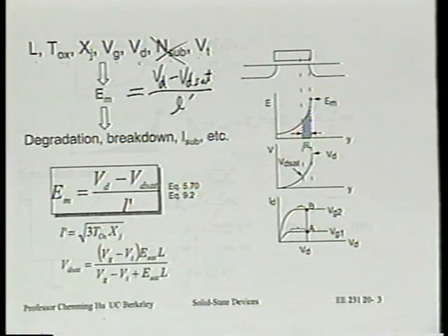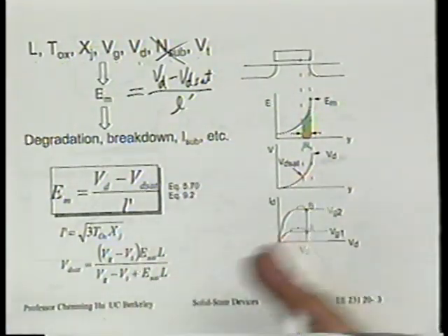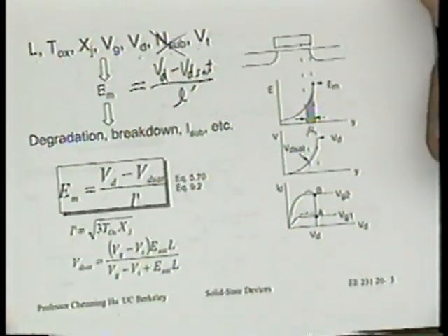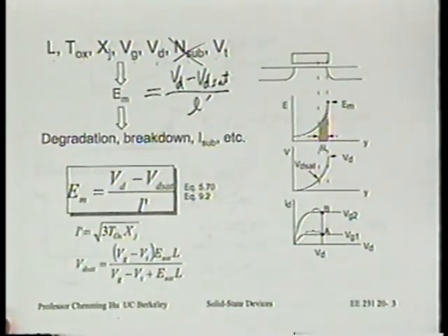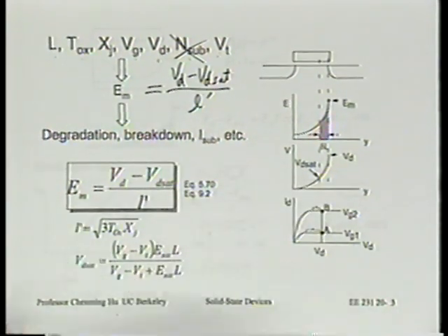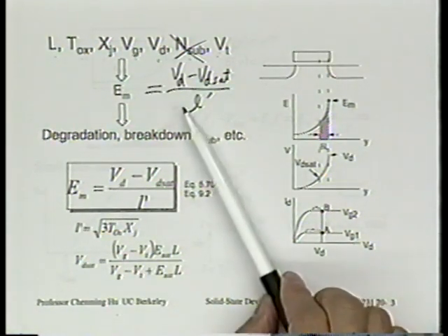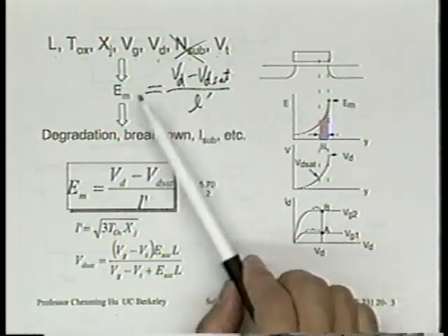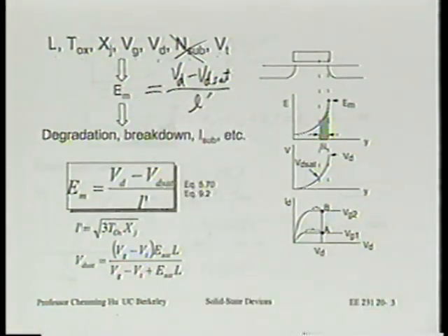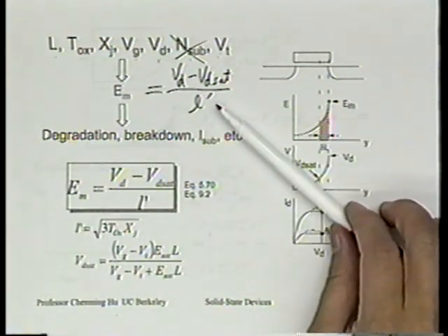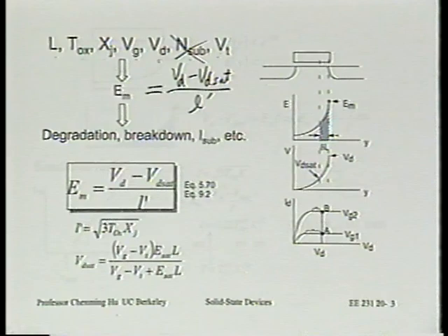Is that correct? Okay. Within the constraint, this is only an analytical model. So if you really want to know EM within 10%, you probably will have to use some simulator to solve the Poisson equations numerically, right? But as a general trend, this equation definitely captures all the trends correctly, all right? And it's more than trend; it's semi-quantitative, giving you a good prediction of what EM should be. Okay. So that's the EM model.